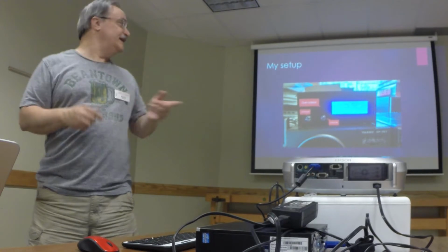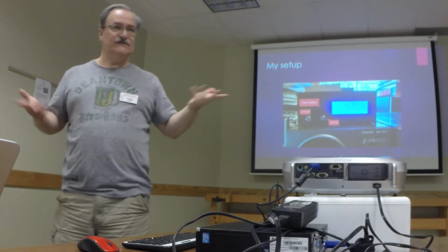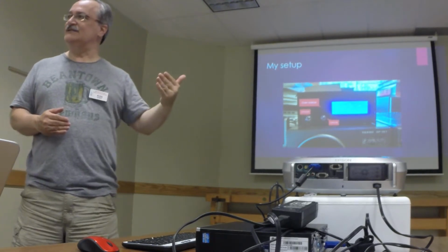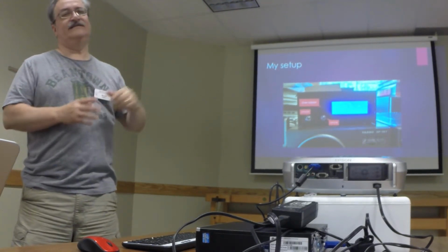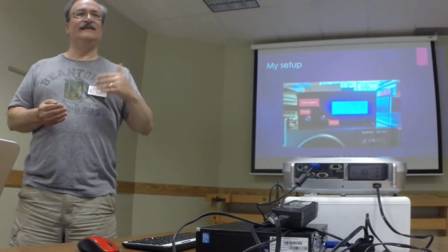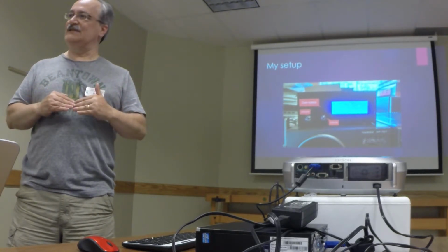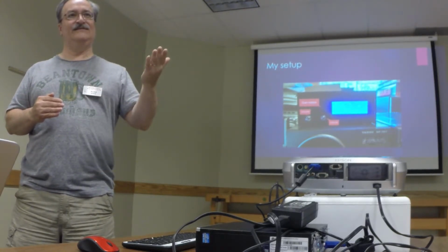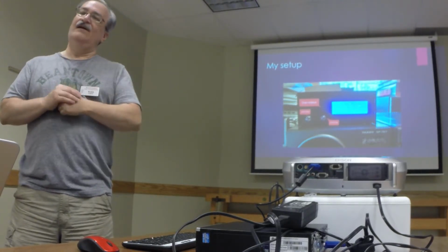So if I push the elevation button, which is the one on the left, up, it goes up 10 degrees. If I'm at 0, as it's showing there, it's hard to see, but it's at 0. If I try to go down, it will not go down, because it has limits. So that's configured in as well. So it knows 0 is the limit. It knows plus 90 is the limit for that particular rotor, and it goes 10 degrees at a time.